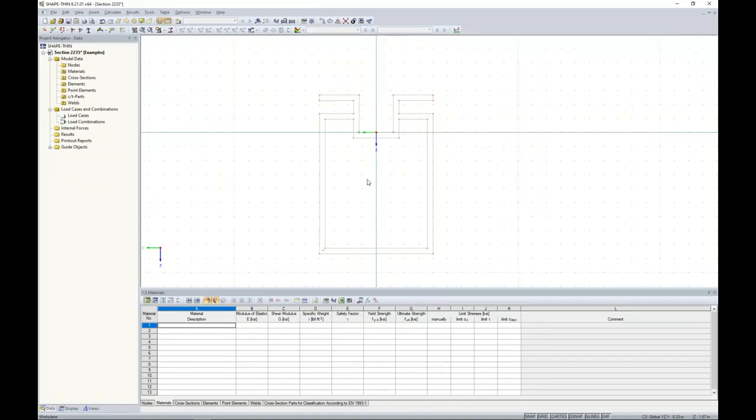Now it's not so simple that we can just simply mesh based on this import here and calculate the cross-section properties. We somewhat need to trace over this background layer again, and that's to determine the width to thickness ratios for eventually local buckling. But we do have some powerful tools that allow us to actually do that fairly easily.